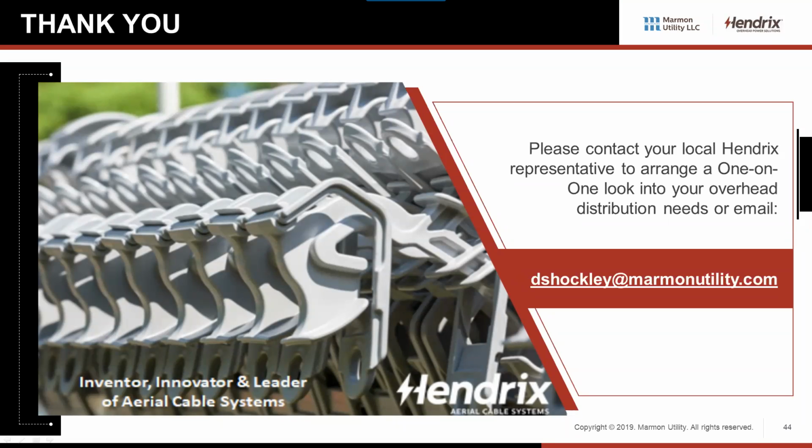From my perspective, I like to leave them open. I like to see them open. Number one, you can see the actual connection. If you ever have to work on that particular section of the circuit and you need to ground it, you want to see that visible break. You want to see where that bare aluminum is, if you need to take a tap off and put a ground on it. Because that's what our recommendation is.